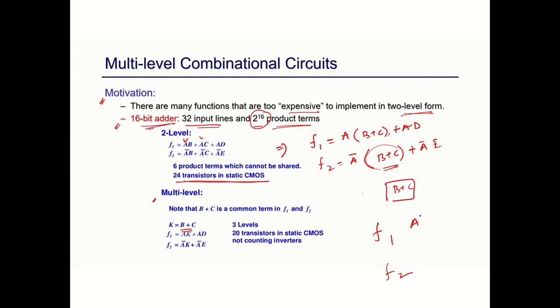So this is the a, and here you can check this b plus c is a single unit, and here one AND gate, another AND gate, one AND gate, and AND gate. So how many AND gates are used now? 4. 4 AND gates are used. But here we have inserted one OR gate in between to just omit 2 AND gates.